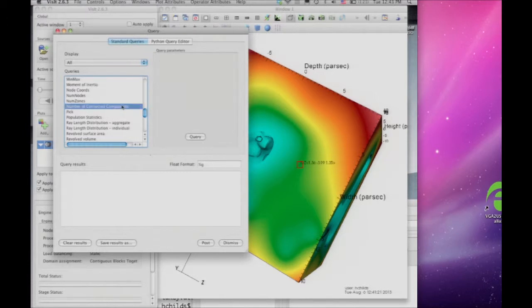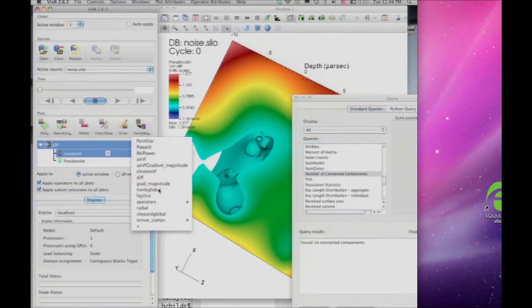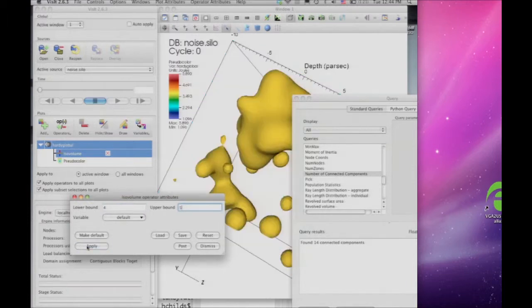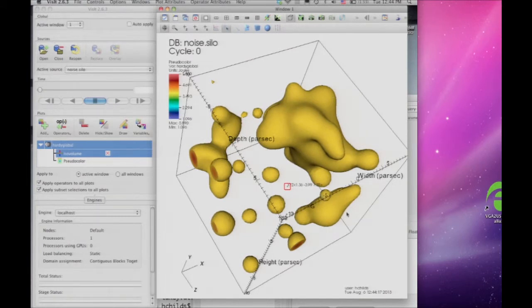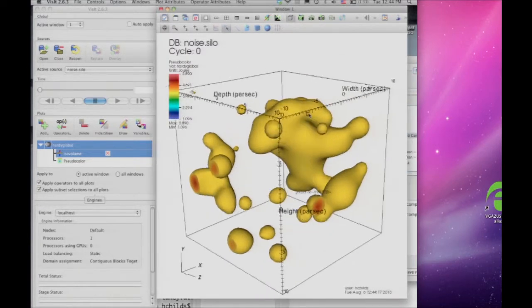I'm going to go to Controls and say Launch the command line interface. So here's the command line interface, and I want to say Query Max, and it gives me the max is 5.88. But if I say Query Max and then Actual, it tells me the max is 5, right? What's awesome about the command line interface is you can automate really neat things. If you want to make movies, you can put them all through Python scripts and interpolate your camera positions, and interpolate effects within the attributes of these operations.